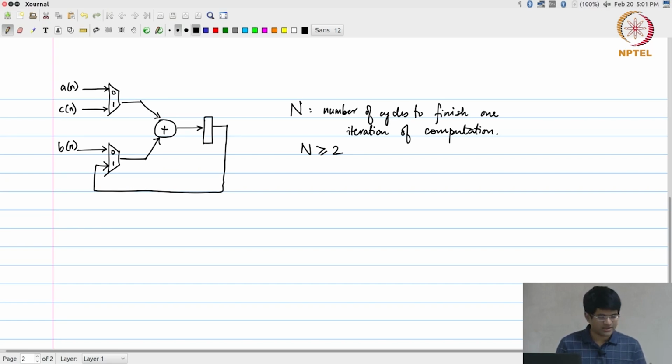One last question to be answered: where and when do I get the output? Okay. So what I am going to say is I will further have one signal out here which I will call y of n, right, and if I directly take the output of that register, that is not really the value that I want for y of n, right. It is going to give me the wrong value because that register on one clock cycle is only going to have the value A of n plus B of n. That is not really the output that I want.